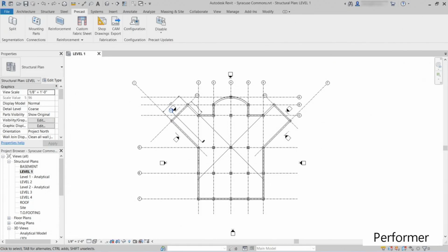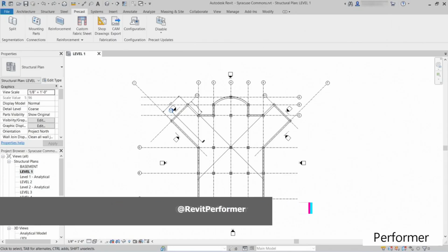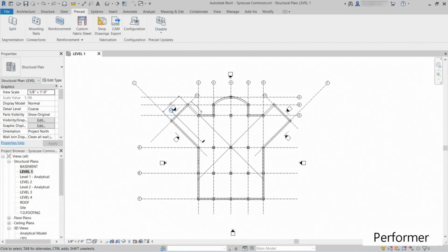Let's continue from our last video. We need to start treating our walls as if they are precast panels. That means we need to go past the point of no return. This step has to be done before any of the other steps can be performed. The objective of this video is to create precast assemblies of our walls by splitting them. It's going to be based on the distances we specified in our configurations dialog.